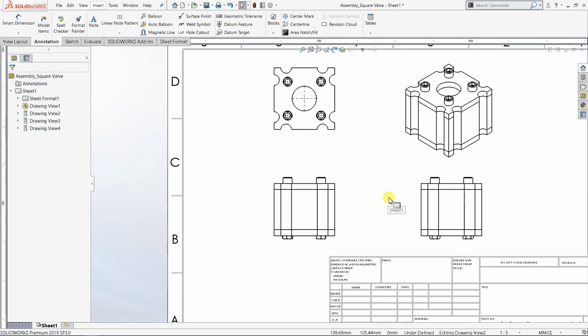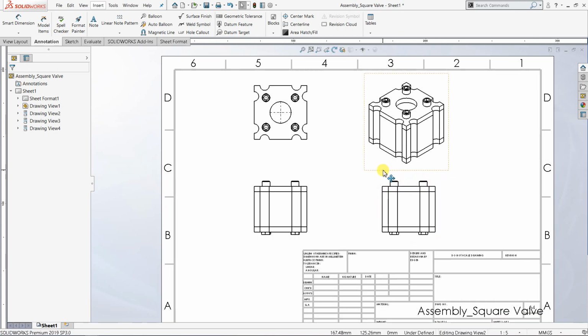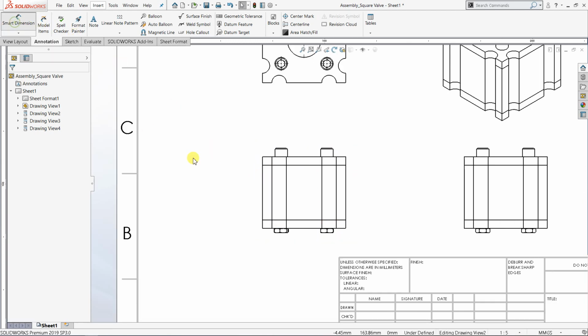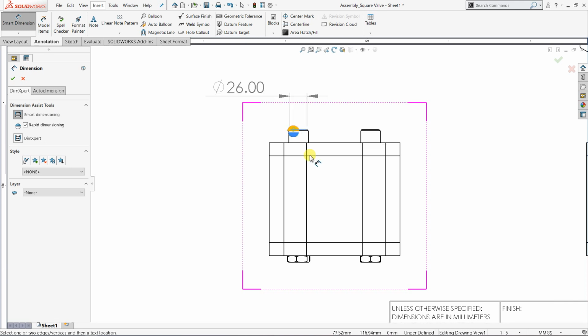Now, under a 2D technical assembly drawing like this, it is also not necessary for you to indicate detailed dimensions. If you would like to indicate dimensions, it is enough to show the major dimensions only. What do we mean by major dimensions? Major dimensions means you can indicate the overall width, the overall length, as well as the overall height of this particular product. So in this case, I'm going to pick Smart Dimension, and I'm going to pick here, from here to here.